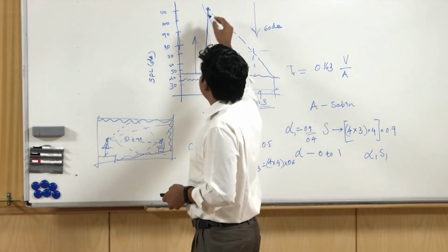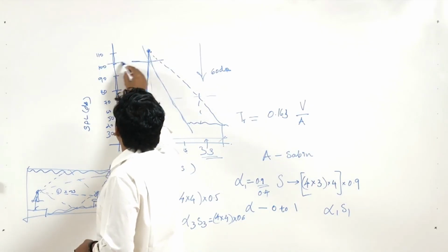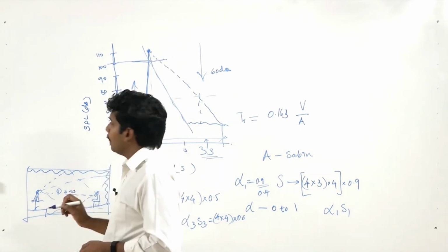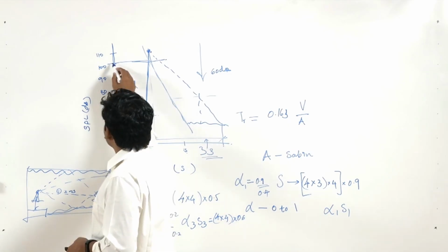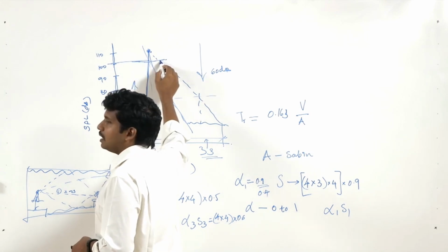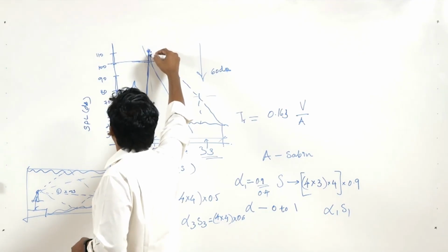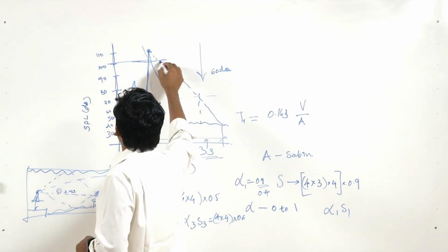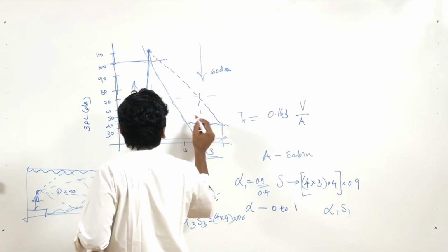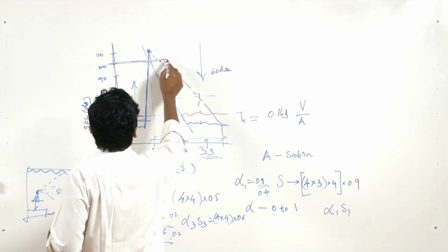Then when you say the peak level, there will also be certain masking here. So it is good practice to leave a 5 decibel threshold here and another 5 decibel threshold here. So now already we are at 50 decibel, and the maximum has come down to say 100 or 103 decibels, leaving certain undulations on the top, because you cannot perfectly reach 110, it may slightly vary. So assume you are at 100 decibel minimum possible. Again, in our auditorium case this is the background, and after the decay it is going to come down to this point. This is the peak level which we are assuming.